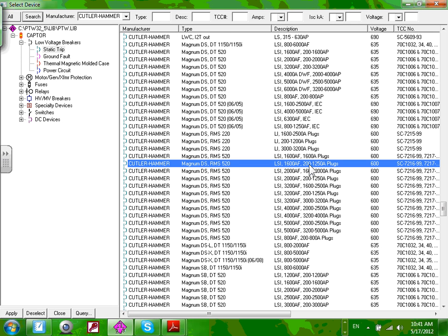Could I have used any of the others and set them up to get me what I want? Yes, but it would be a waste of money. It's a waste of money to use a frame of 4000 amp to get 200 amp out of it. Okay? So when you buy the frame, it's like the rating of the container. The frame limit is the plug.